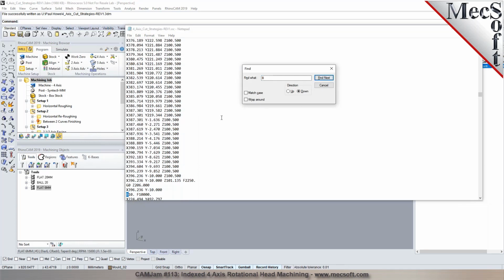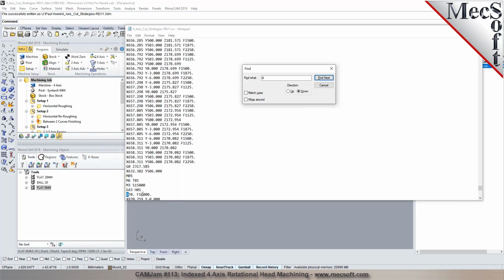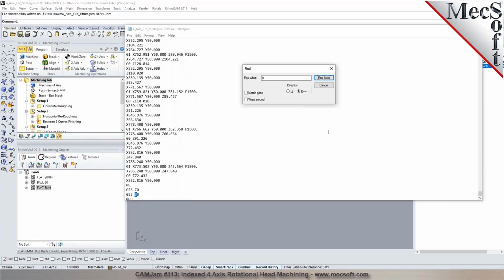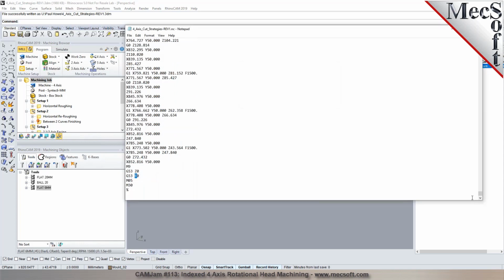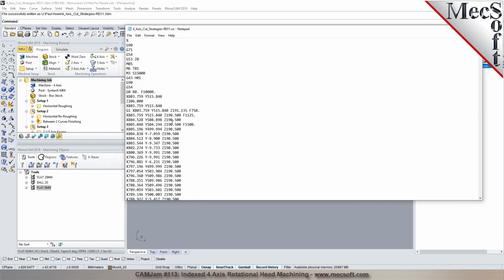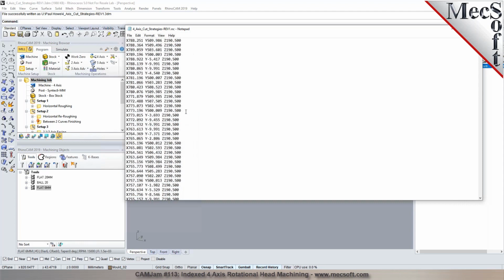And you can see the B values, so it goes to 10 degrees for the B. Yep. And B goes to -10 for the other side. And then we have B going to 70 degrees to cut the other face. Yes, to do the end. Yep. And then B0 at the very end before you cancel it out. And in this case, we haven't applied any gauge length in here. So we'll show you an example with a gauge length.